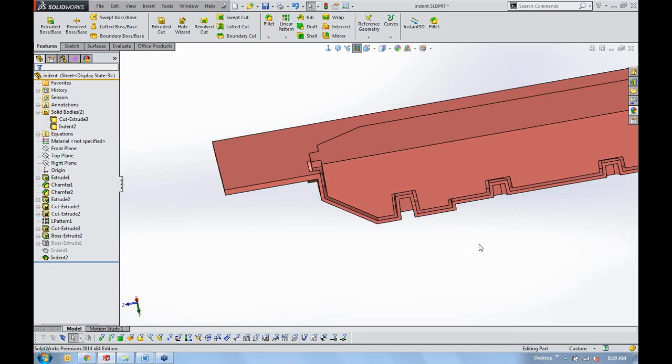There's a lot of applications where you can use the indent command. Again, this is different than the cavity command with a scale, because it's not actually scaling my model, it's just offsetting all the faces, in this case 1 millimeter. So that's kind of a neat tool that I think is fairly underutilized, and hopefully you guys can find a need for that at some point. That'll definitely save you some surfacing if you use it at the right time.